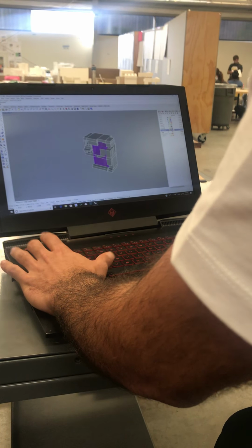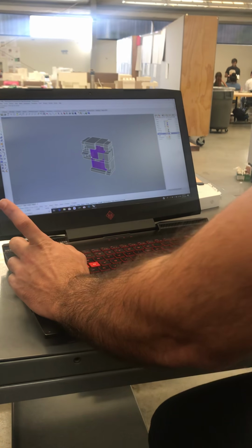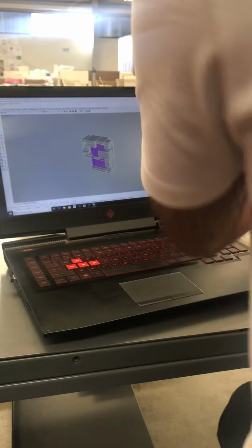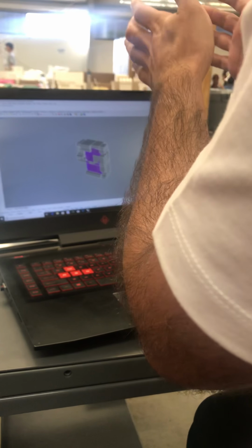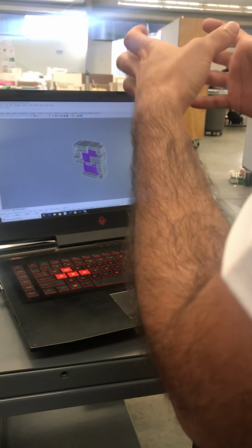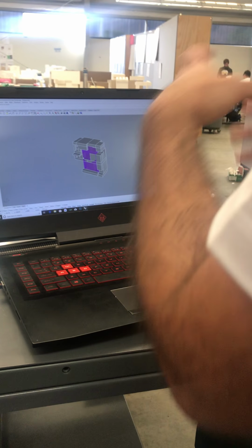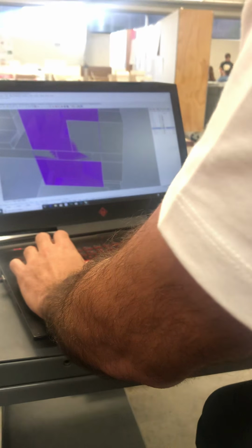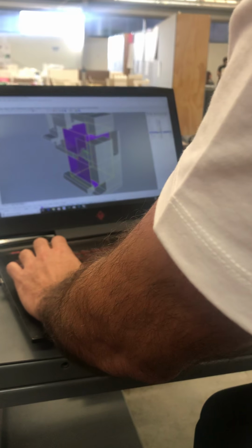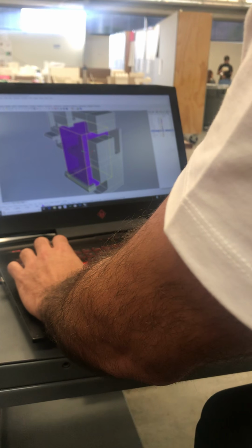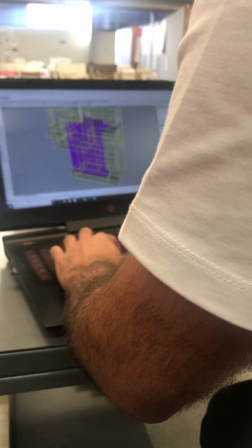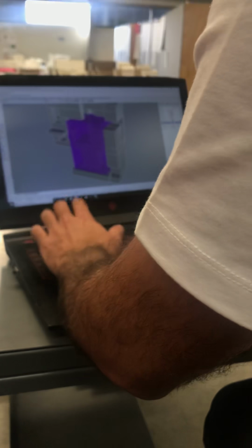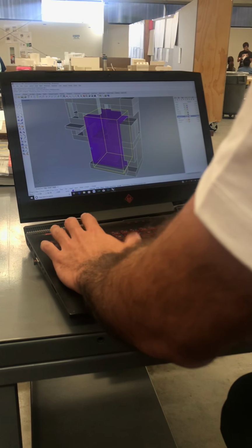So I hit enter and it failed. So I don't know if any of you have had this problem, but basically sometimes it has an issue when it's going to subtract when 2 faces are overlapping. Like when the box that's subtracting is overlapping the faces of the model. So to remedy that, I might just move it over one module. And now it shouldn't. Boolean split. I'm going to select my cutting surface,